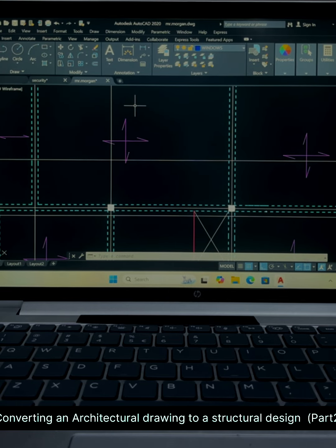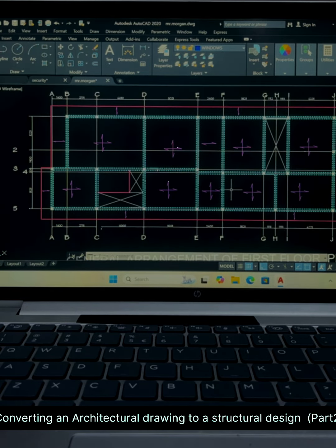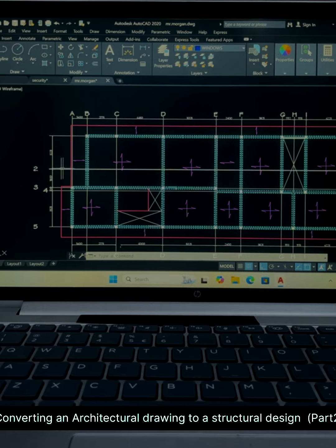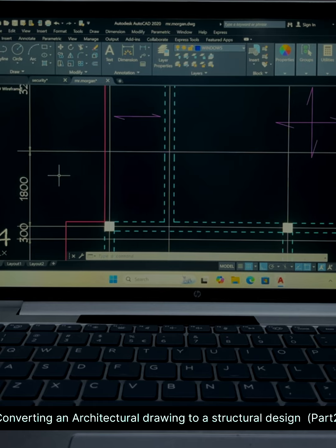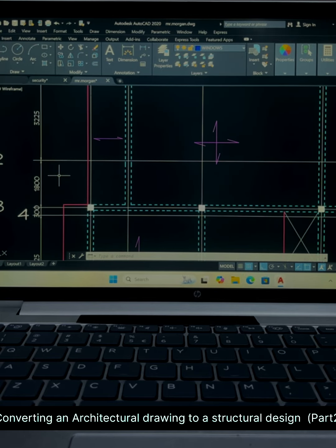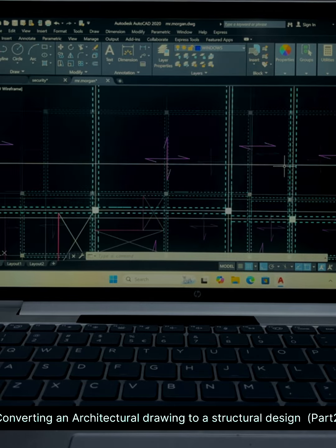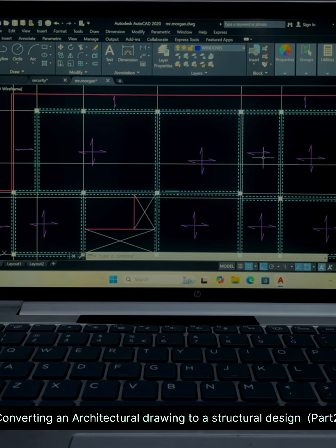This is the symbol showing that a slab is in a two-way direction, while in this area here, this is 2.4 meters by almost 5.2 meters. If you check the Ly over Lx ratio, here is a one-way slab.